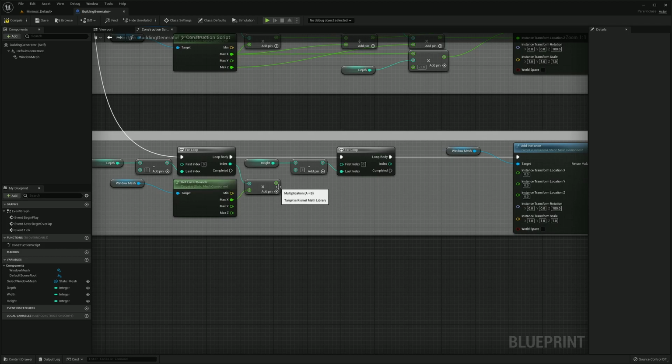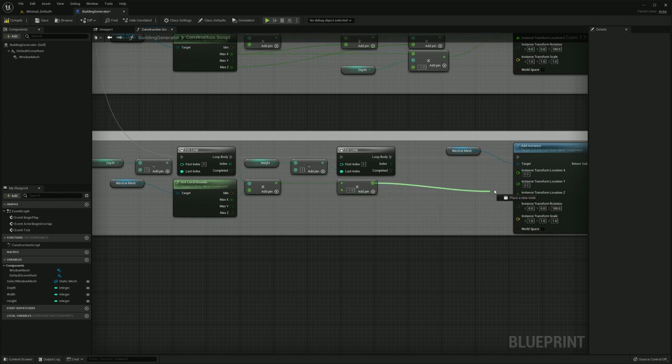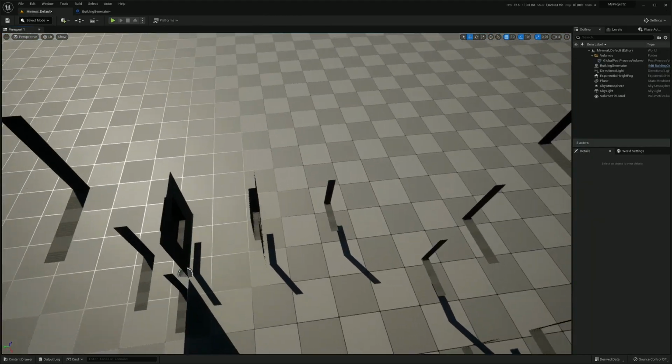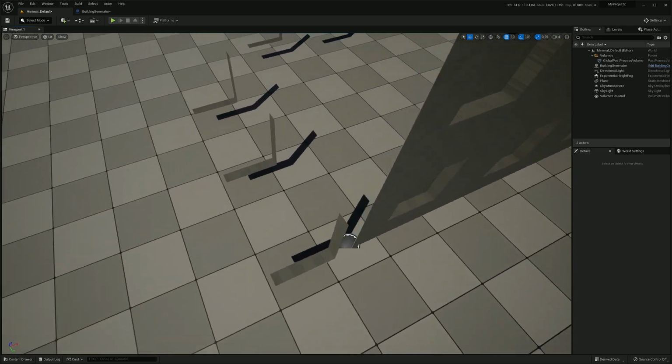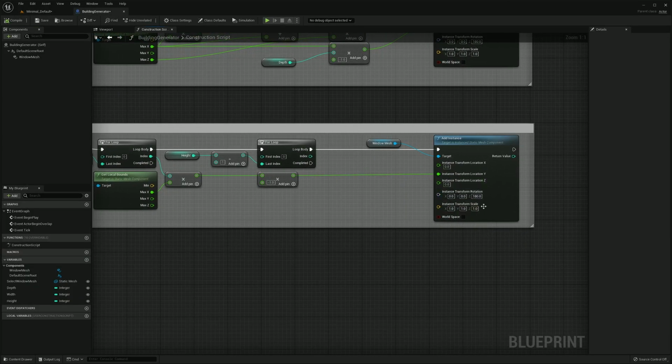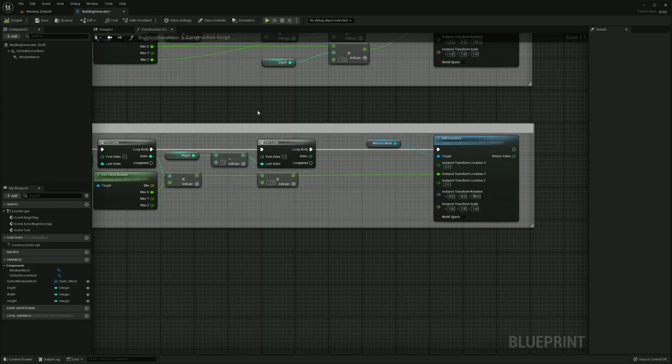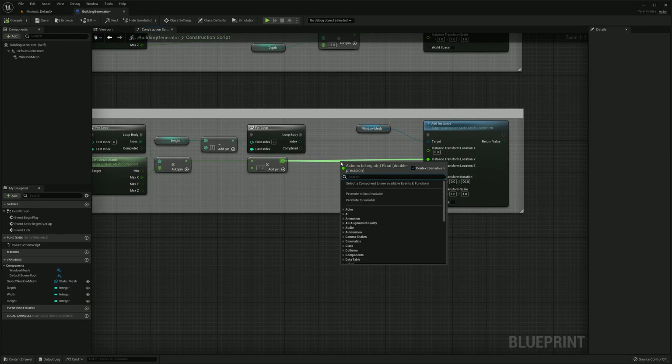We need to invert the y-axis, since it's going in the negative direction. We also need to change the rotation. And offset the y-axis with 1 mesh width.